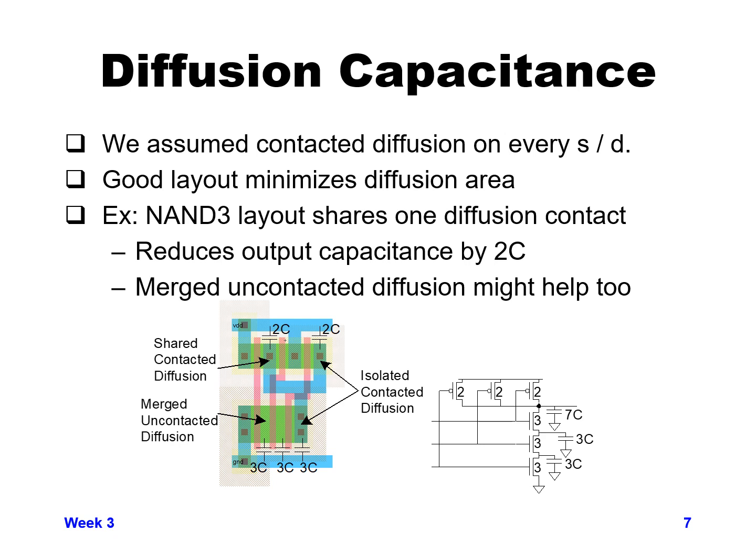Likewise, for the NMOS diffusion, since the NMOS transistors are connected in series with each other, they can get their connection strictly through the diffusion itself. They don't need to have metal contacts and have separate drain and source. They can have a merged drain and source that actually causes that area between the two gates to be smaller than it used to be, and so that capacitance value can actually be less than it would have been.